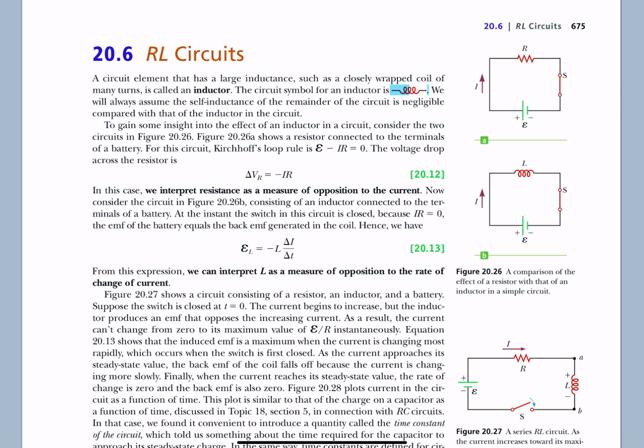So the rest of this discussion requires you to remember what we meant when we talked about the back EMF, the pushback that happens when current goes through a wire, because as soon as current goes through a wire, it induces a magnetic field about that wire, which is usually nominal or can be ignored unless the wire is in a coil. If the wire is in a coil or a solenoid or a bunch of loops, each loop is in such close proximity to an adjacent loop that as the magnetic flux lines expand or collapse around one loop, it affects the current in the other loops.